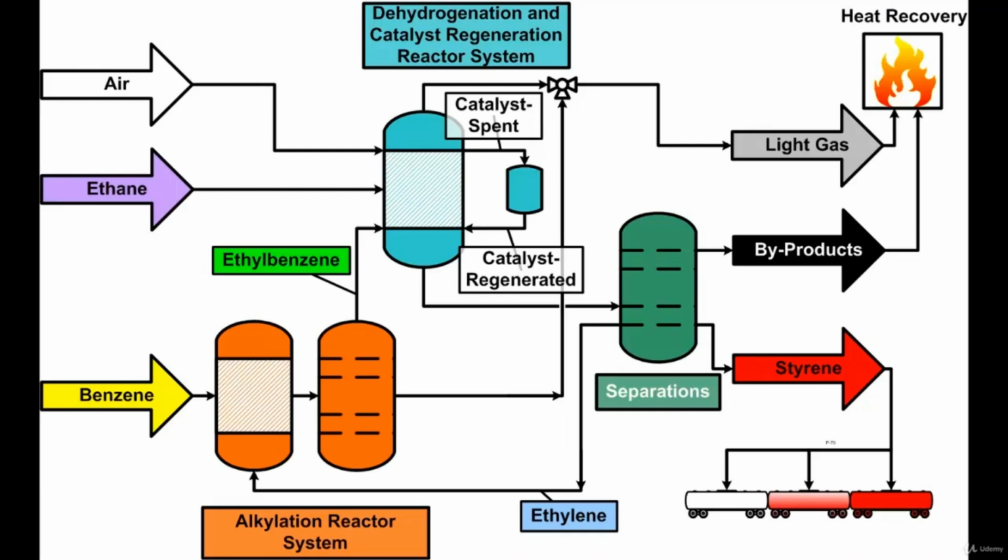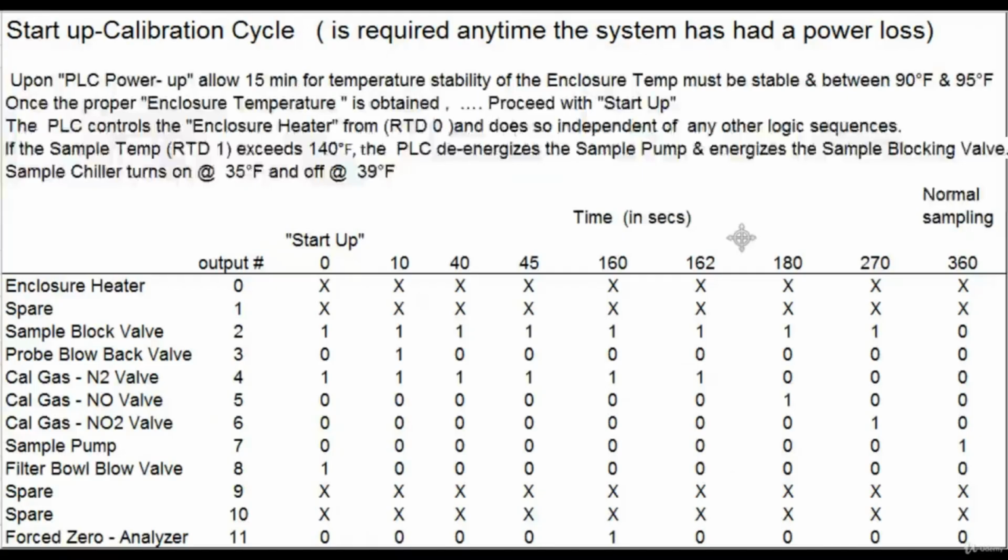So before we start programming, how do we imagine the process? How do we understand the process? And visualizing the process with something like a visual flow diagram, a cause and effect chart, or even a Visio diagram is a really helpful tool in knowing what your program is going to need to look like, how to divide it up between various ladders. And really, the more you can envision the process from the beginning, the easier your program will be to write.